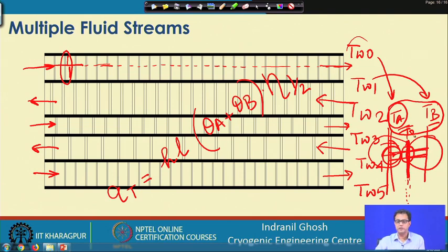But it may not be the situation for every case where T A and T B are not the same. So, depending on the T A, T B, we may find various kinds of configurations where we will find that the extremum, or this minima or the maxima, is lying within the fin, outside the fin, and of course, it may be there is no minima at all.